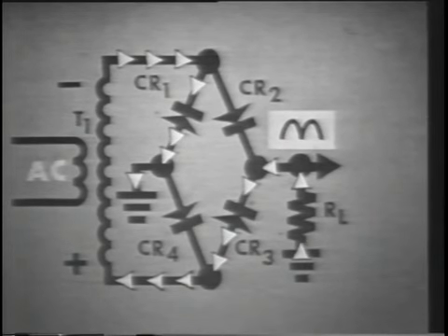From the schematic, we can see that this narrows the trouble down to the 4 diodes, one of the 4 diodes, or perhaps one of the common connecting wires to the diodes. Well, the diodes are the most likely source of failure, so we could check each of them for an open. With only half-wave output then, look for an open diode as the most likely source of the trouble, or perhaps one of the connecting wires might be open.